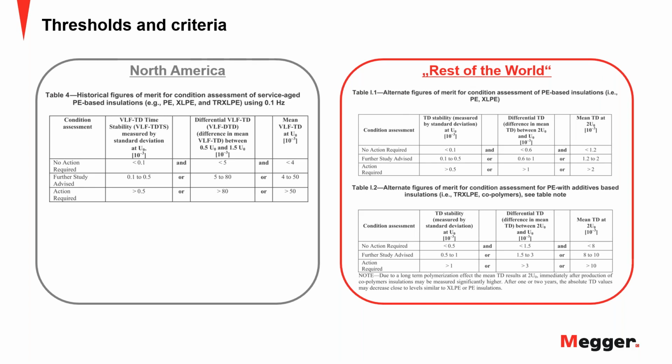That's a very good point, because many times people are not necessarily aware of it, because some of the sinusoidal test sets have, let's say, a milli or microamp meter, right? And it's sometimes associated that it means it's a leakage current. It's not the leakage current, it's purely the charging current you measure over those. And on a continuous AC sinusoidal wave, you cannot measure leakage current like Bob is saying. You can only measure the sum of leakage and charging and polarization and everything, right?